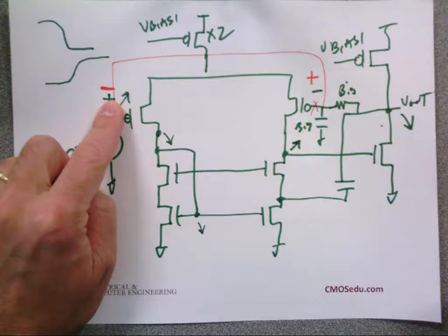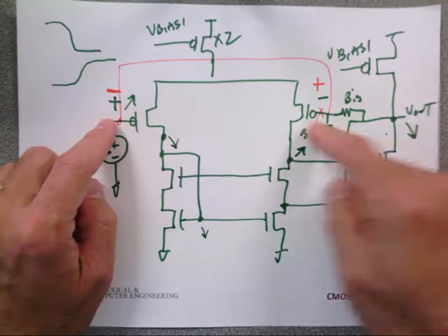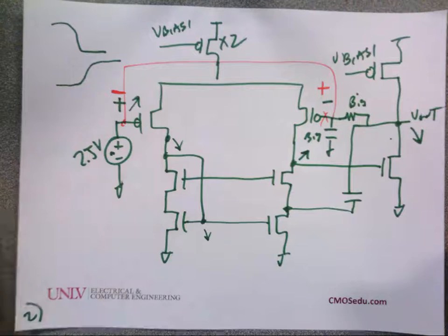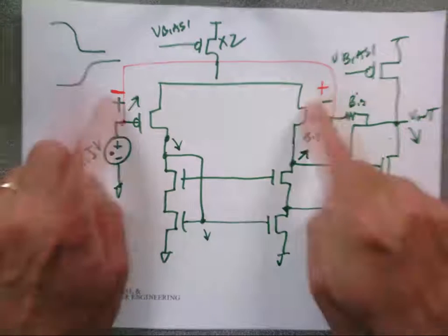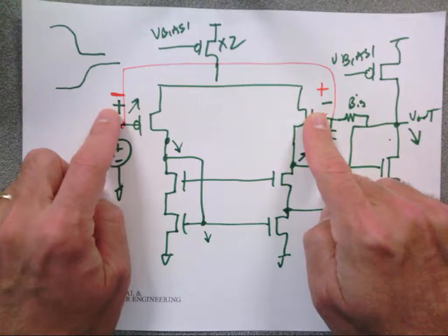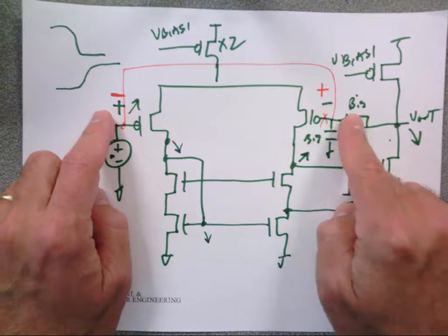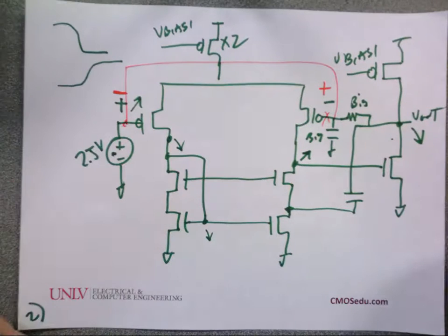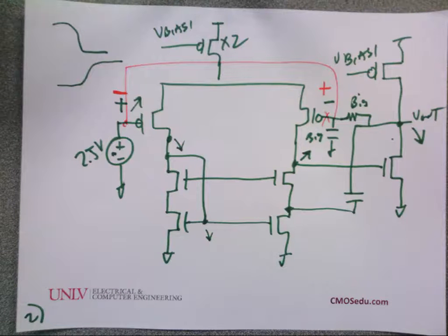If you say this is the plus terminal and it had been working, then there's some weird state it got into where it's biasing up right, and when you change something minor, because of that plus and minus inversion, it stopped biasing up right. Even positive feedback can be stable at times, right? An example of that is what? Yeah, because we killed the gain with the resistor. And then if you tweak something like we add the capacitor, it can cause it to be unstable, even though everything else is the same and working perfectly. So I don't know what to say.